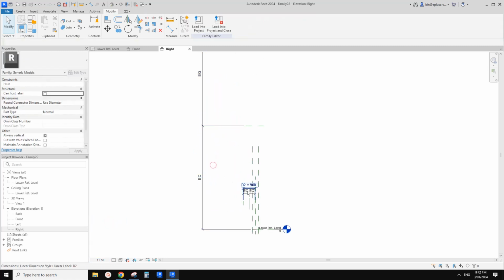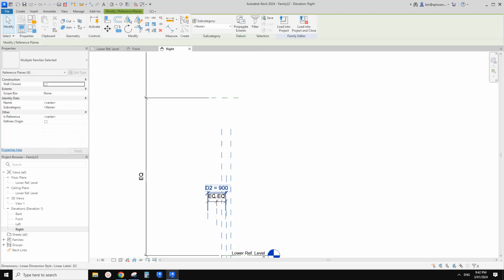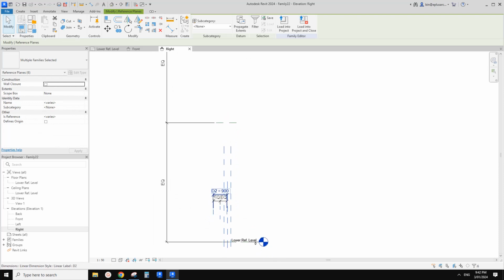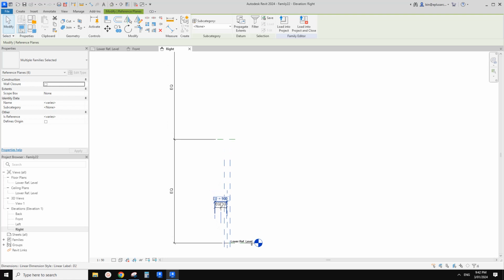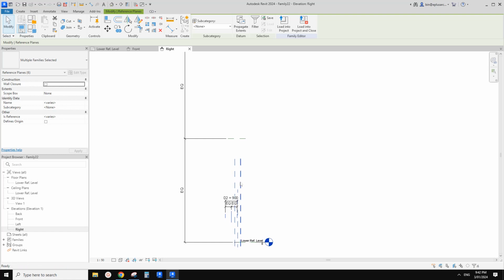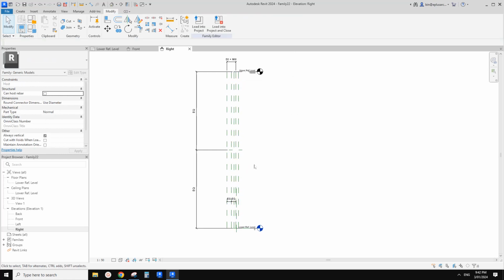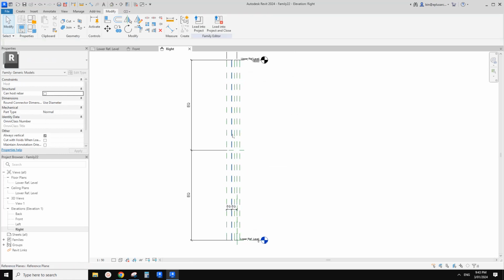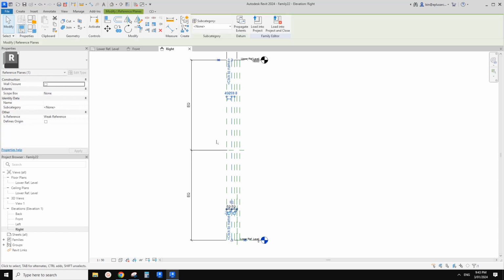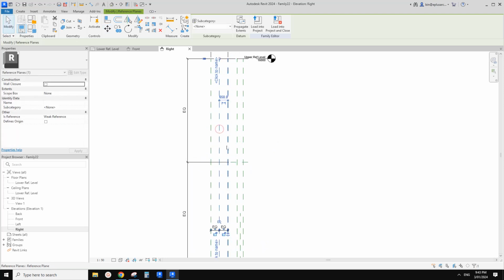And also we need to select this reference plane. Sometimes you draw this reference plane quite short, right? Although the actual 3D extent of these reference planes is infinite, it's easier if we just right click and use maximize 3D extents. Okay, so now this one's center of the middle profile. Let's just move it to the left a little bit more, so separate them.